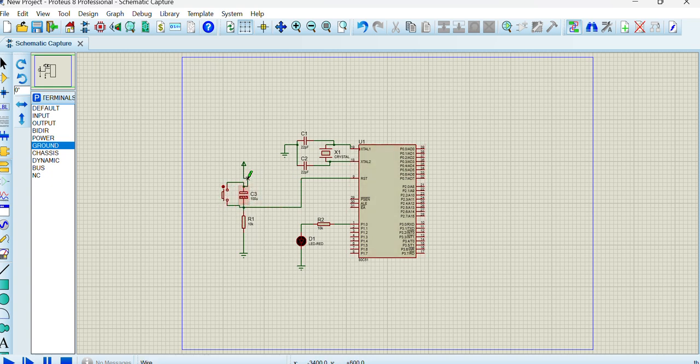So whenever we turn our power on, voltage changes from 0 to 5 volt. That change from 0 to 5 volt acts like an AC signal for this capacitor, and this capacitor will directly get short circuited and our power supply will get on the pin number 9. That's why when we turn on power, this 8051 microcontroller will become reset. So that is called power on reset. Okay. So this happens when power is turned on.